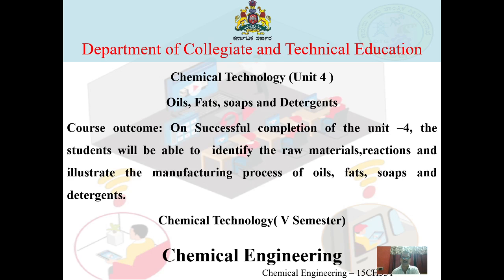The powdered activated carbon is mixed thoroughly with the yellow glycerine, and it is filtered on a rotary drum filter, so that the activated carbon along with the adsorbed impurities and color forming materials is obtained as a filter cake, which can be taken out and discarded. The filtrate is pure water white glycerine of 99%.